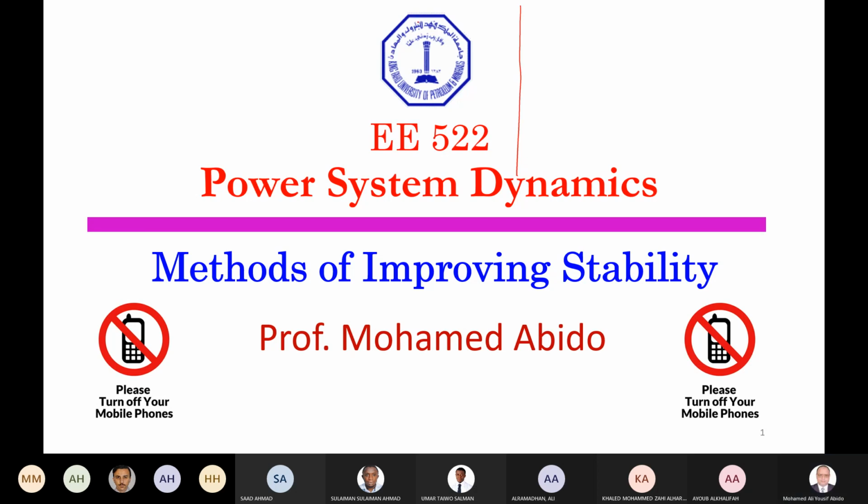Ramadan said that we can install FACTS devices or new transmission lines. FACTS devices. Yes, you are right. This is one way to improve. You have series compensation, you have shunt compensation, SVC or STATCOM, the shunt compensation, you have TCSC, thyristor controlled series capacitor, or switched series capacitor also.